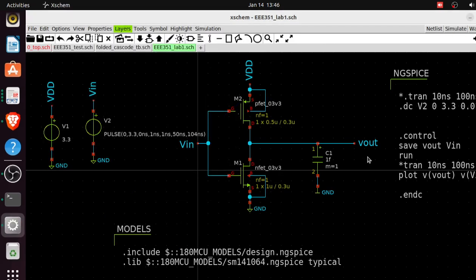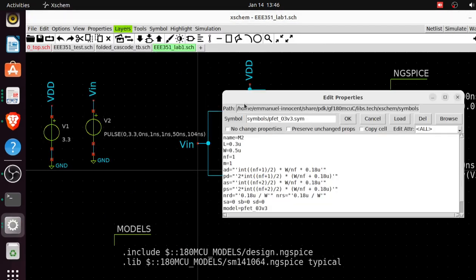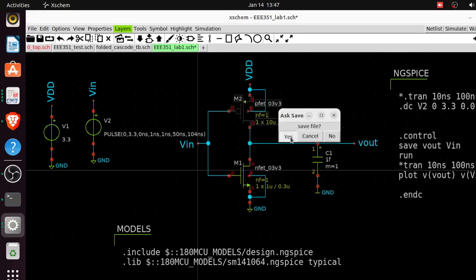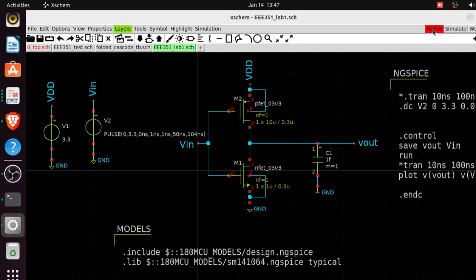It won't be robust for the noise margin for input. So let's try to increase it far more. Let's make it larger, not the length, the width. For the NMOS it's 1, right? So let's say the NMOS is 1, and let's make this, say, 10, if there is a device that has such a definition.